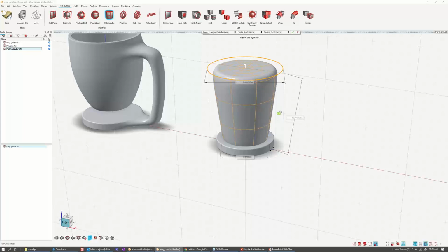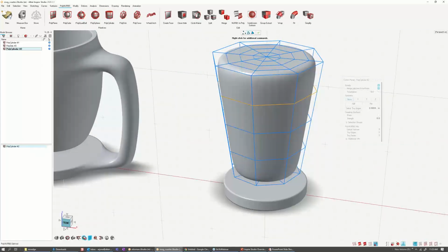But before that, I want to turn off any snaps, because whenever I'm modeling with polygons, snaps are a bit too clunky and I want some fluidity. So I'm going to turn off all the grid snaps here, but I'm still using other snaps. Here I have this first loop. I'm going to hold Alt and click on it. When I click, of course, the entire loop is selected.